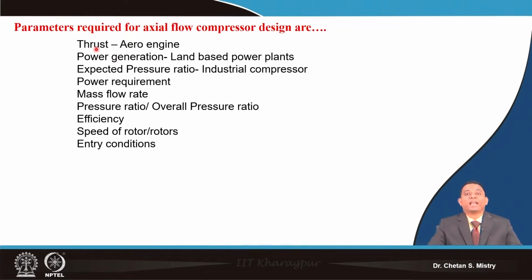Next is what we call entry conditions. Where I'll be using my compressor, that is what is important. Suppose we are designing our HP compressor, then my entry condition will be high pressure and high temperature. When we are designing our low pressure compressor or, say, the fan, there we will have entry conditions of lower pressure and lower temperature. So entry condition is also equally important. Suppose we are considering applications for industries, there also the pressure and temperature at which my fluid is coming is of major concern.